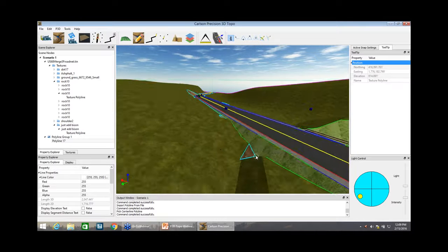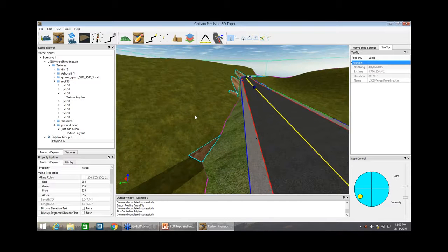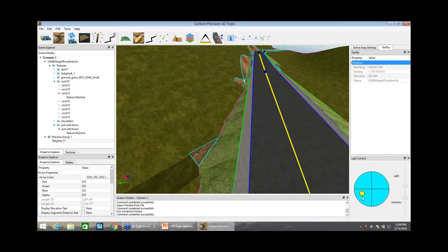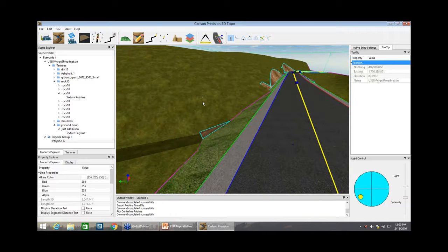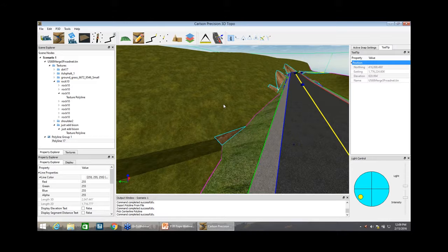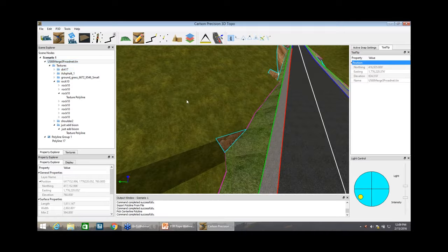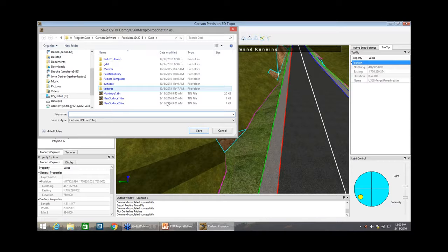Now I have another problem here. And by the way, in addition to saving a land XML file to give to somebody else with that improved slope area there that you fixed up, benefiting from all this texturing and wonderful 3D viewing where you control your sun position down here and can learn a lot from these border polylines, you can also right away click on the surface and let's see, click on the tin actually, and when you right click, watch this, you can save export the surface as edited and look at the file types here.